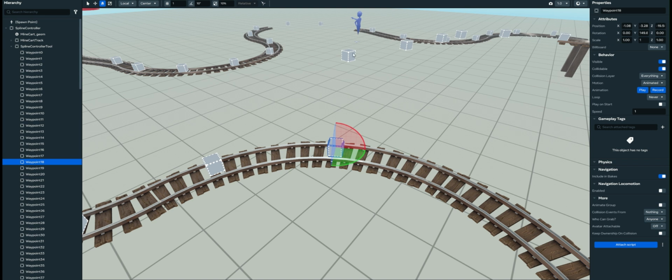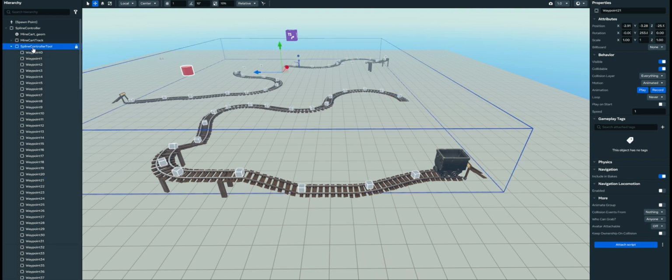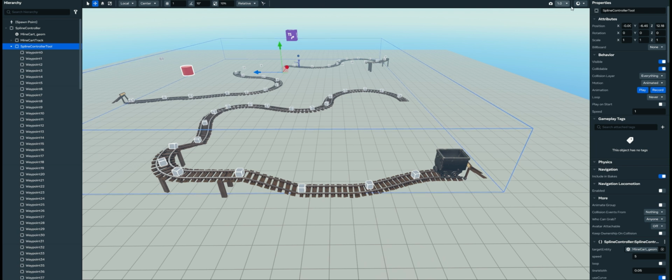Next, we'll copy the position of a waypoint on the current track and use that to reset the next waypoint back onto the track. You can paste the position on several stray waypoints and then work on positioning a group instead of doing this process one at a time. After the new track has a sufficient amount of waypoints added, determine the last waypoint on your track and set the limit. Notice that our waypoints start with 0, therefore subtract 1 to get the total count.